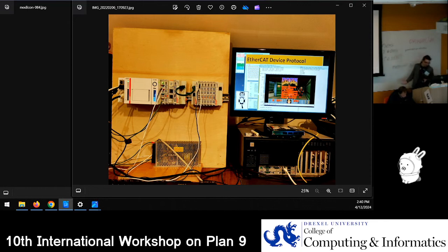And Modbus is one of the first ones. It was developed by Modicon. It's very simple, it transfers registers or bits. And registers are 16 bits. Originally, the old Modicon machine was a big Endian word machine. And so you just quite literally had a 64K word space, and you would just copy registers or memory values from one machine to another.